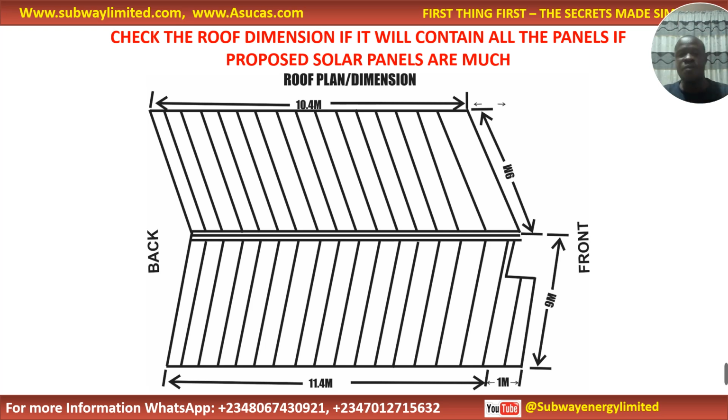The roof dimension will ascertain whether that roof space will be enough for your proposed solar system design. Because I've already said that the roof dimension affects the size of the solar system you give to a client. Remember, the roof is where you mount the solar panels, and if the roof is not big enough and you are having much storage, much solar battery, you will not have enough power from the solar panels to charge the solar battery. So that means you need extra space to mount the solar panels. That is how the roof affects the size of the solar system installation.